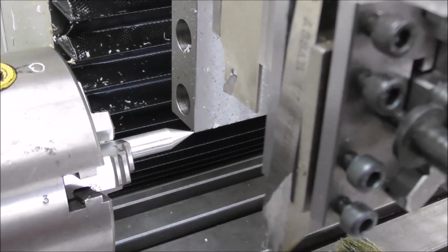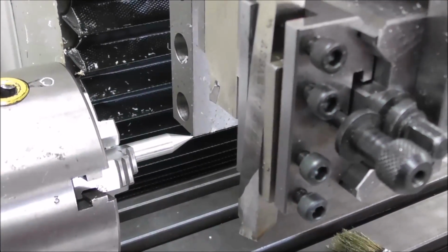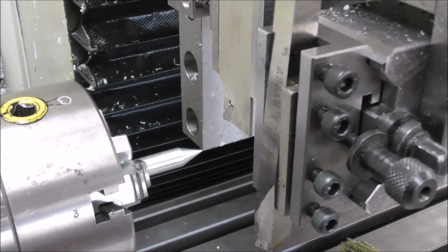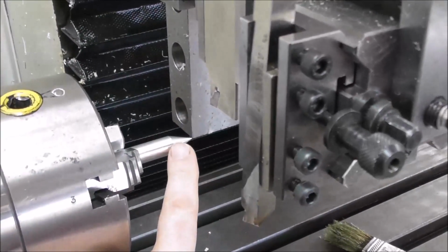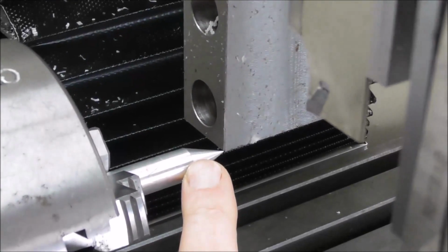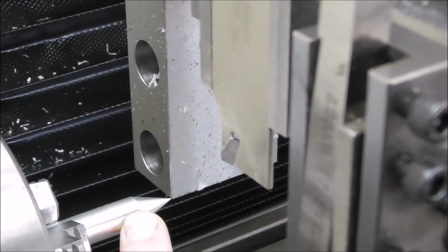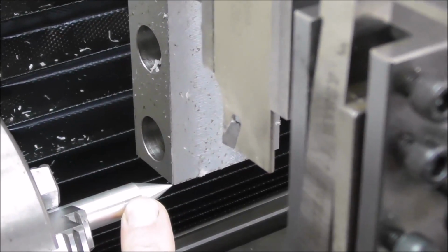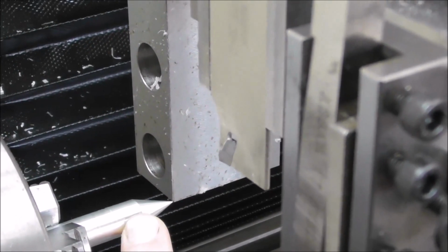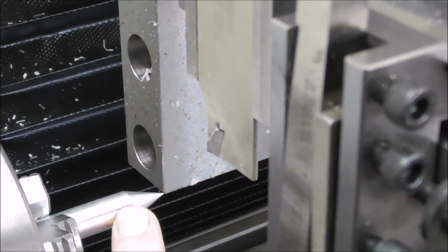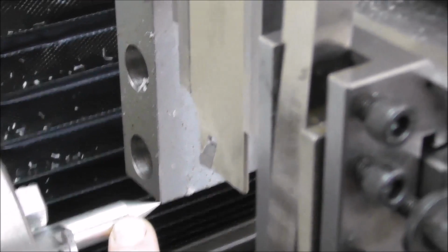Now the advantage of having a non-tool edge for your reference, for your work offset, is that you can find it back again irrespective of whether you still have that tool in there, or whether it's been sharpened, or whether the tip's been replaced, or the tool's been shifted. So what he uses for his master tool position is something like this, and that's worth considering for certain types of work. It could be an advantage to call that tool 1 master tool, no offsets on the tool table. You move from your reference position to that position and set 0, 0 on your main DRO screen. And you might want to call that tool 1 or tool 27, but just stick to it, whatever you decide to call it, and there'll be less confusion in the future.